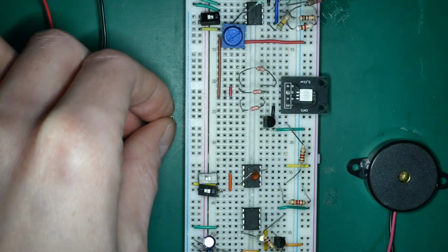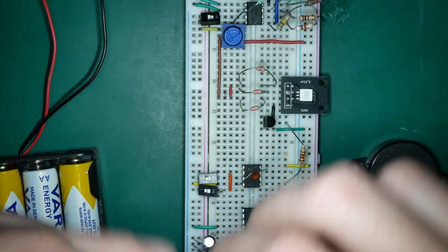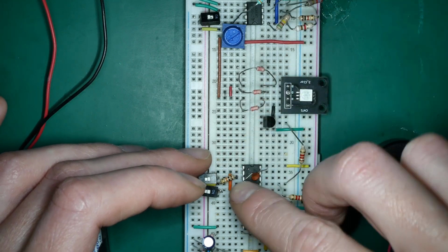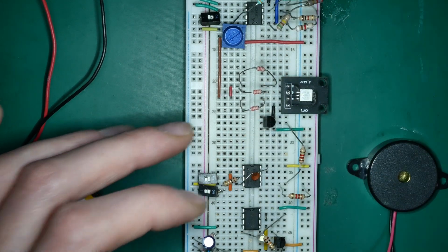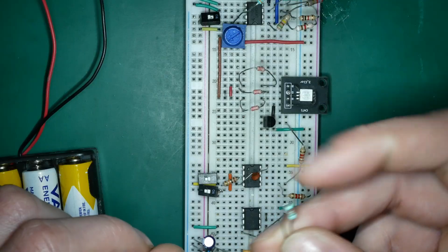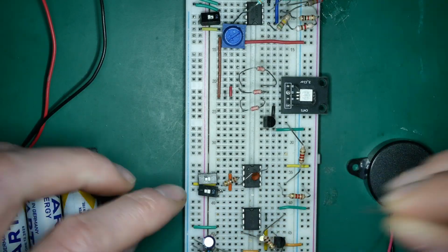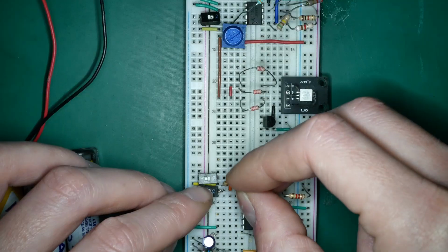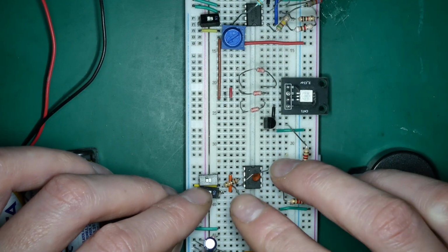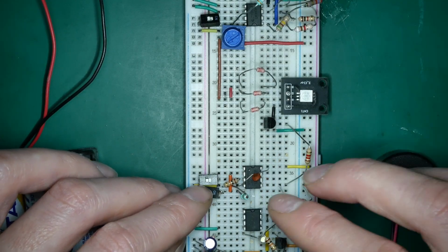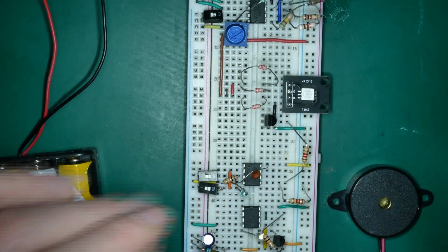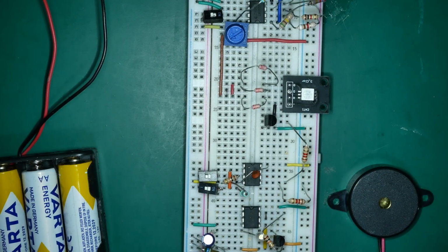Now I will place back the resistor. And I will add another resistor 10K, or in my case 11K, between the ground and the switch, like this, and that's all we need. Now let's move to the Microchip Studio.